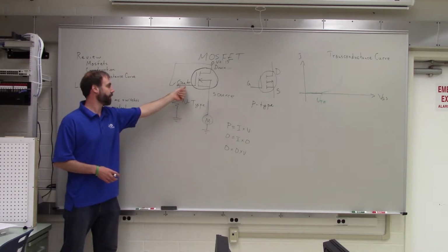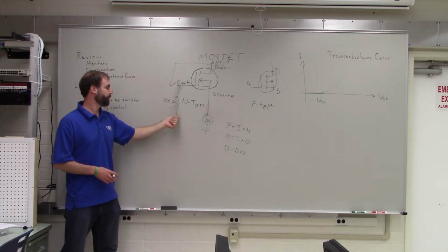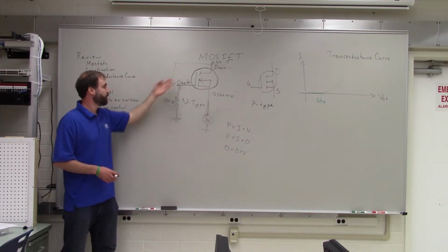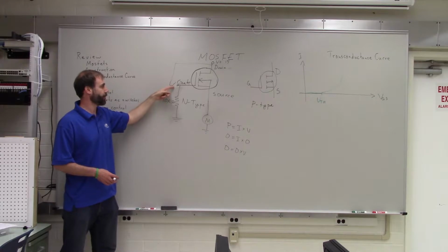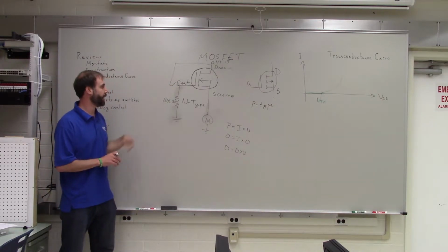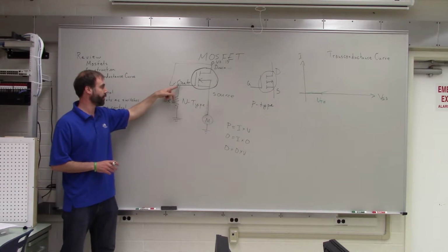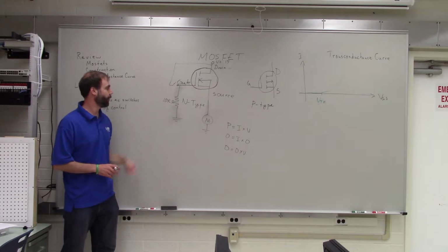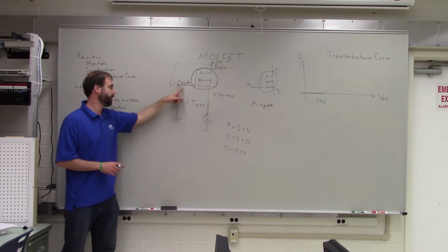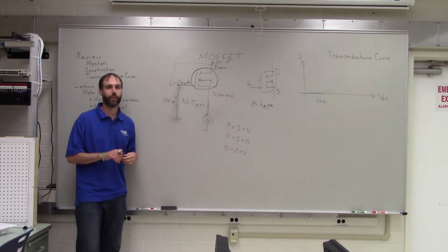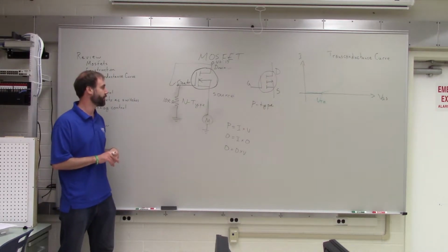So it sets the gate voltage to a known level, 0 volts, when the other switch is open. So then any stray static electricity that might end up on the gate immediately gets drained through this pull-down resistor to ground, and the gate voltage stays at 0 until the switch is closed again. So that's what a pull-down resistor is.